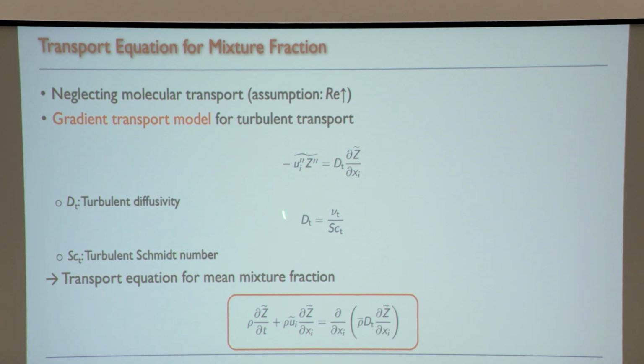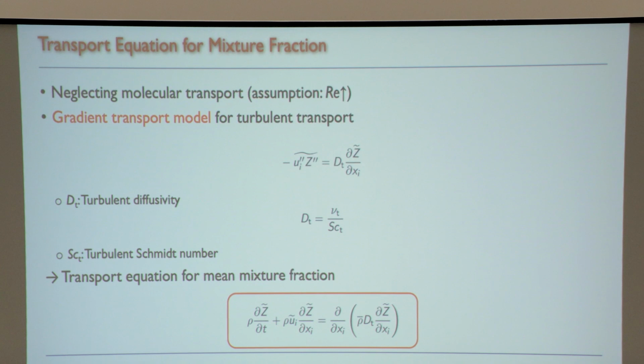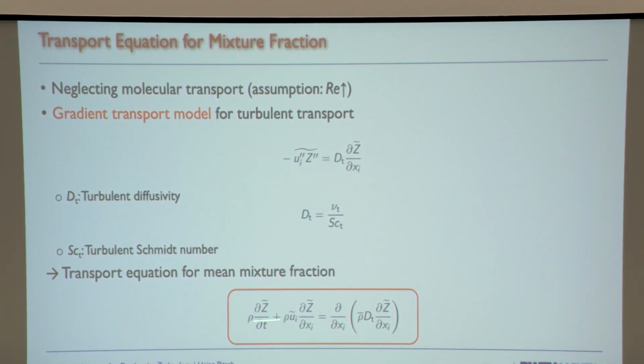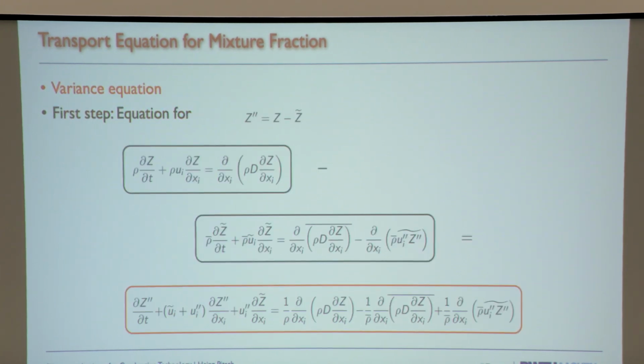And so how do we express this? Sometimes we just set it proportional to the eddy viscosity, because it's the same eddies that cause the mixing in the momentum and in the scalars. And there's a proportionality constant, the turbulent Schmidt number, which is also order 1, and could be a fit parameter for tuning a model so that it matches the experiment. And so then we get an equation like this, and you see this is now closed, everything known.